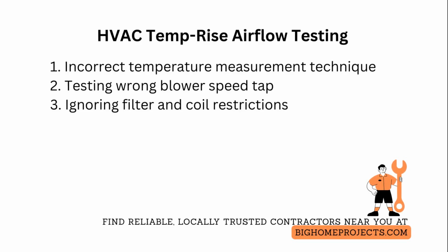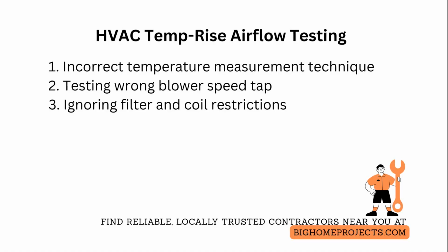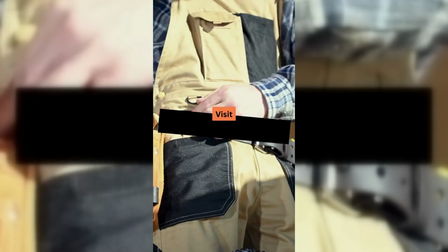The third issue is ignoring filter and coil restrictions that reduce effective CFM and skew Temp-Rise calculations. Fix by measuring static pressure across the coil and filter, cleaning or replacing obstructing elements, and accounting for those losses in your sensible heat input.